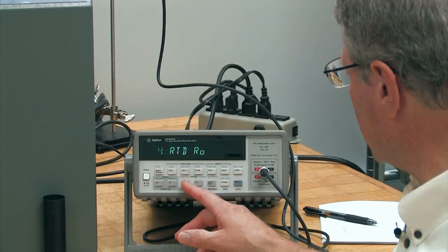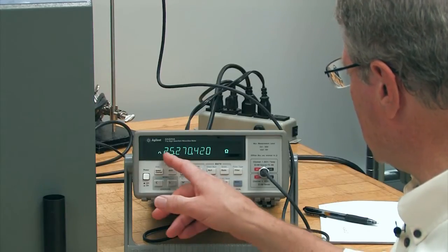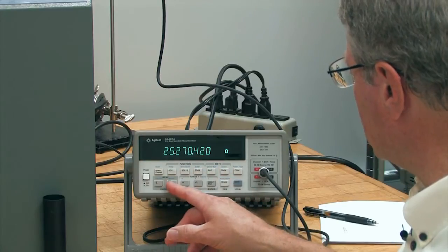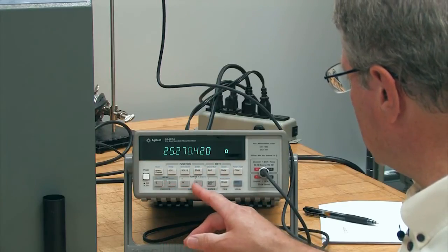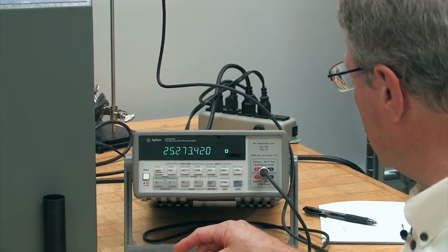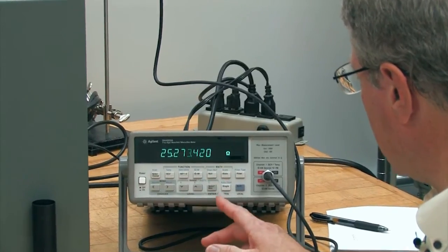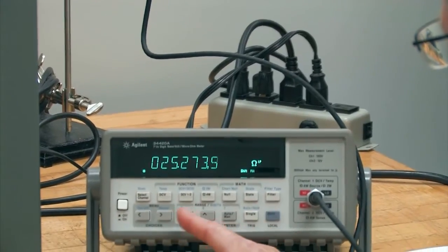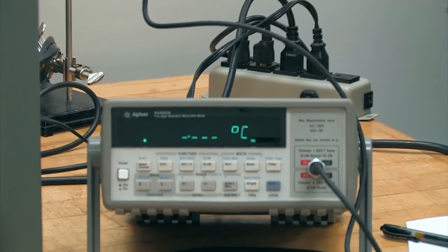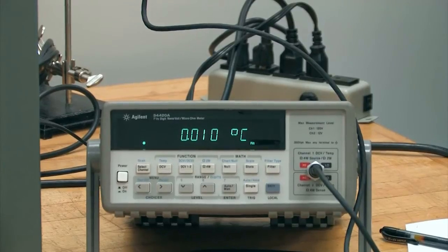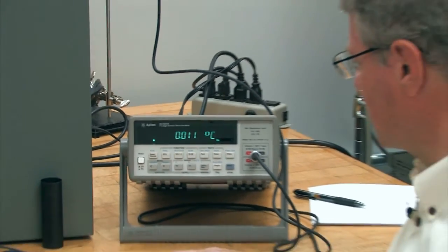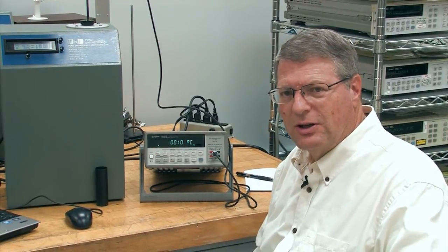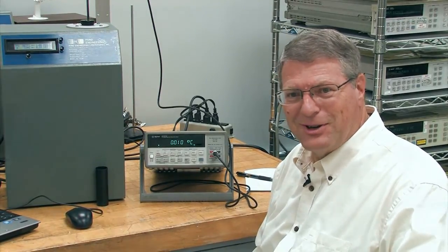Okay, so I'm going to go in and see what I've got set up under the RTD. What did I set it up as? And it looks like instead of a 25.2704. Okay, so I want to come across, take that digit, and bump it by 3. That was the measured value. If I enter that, okay, now I'm going to go back to temperature. Up, and look at that. It's 0.01 degrees C with a 1 or 2 bouncing around on the least significant digit. So it seems to work.